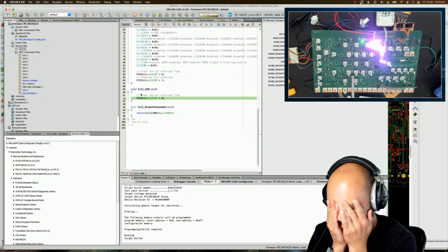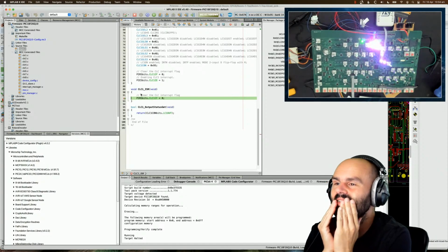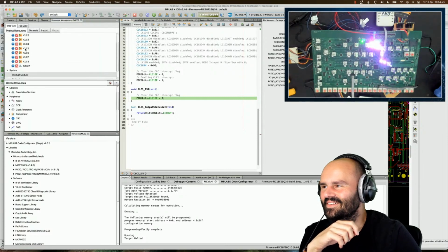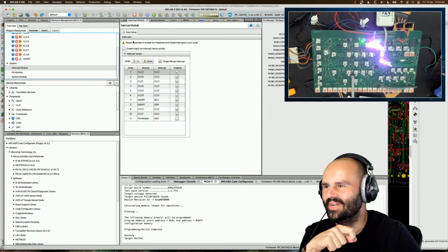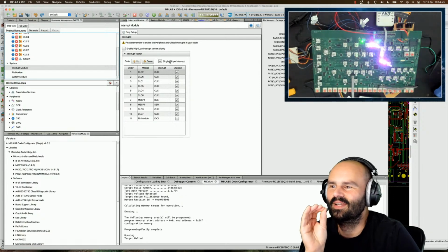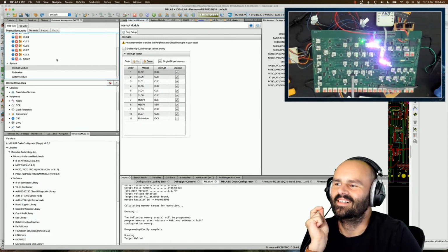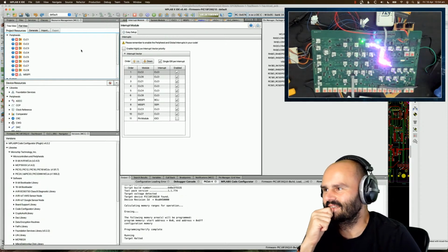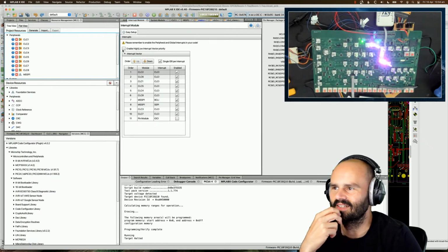But oh my god, I can't believe that it took us all this damn time, all because we missed this one little hilariously lacking warning here: please remember to enable global interrupts. Listen, if you've let me tick this all on and you generated that config for me, you really shouldn't have had to do that. But I think I get why. I know MCC does generate the main for you, so no excuse.